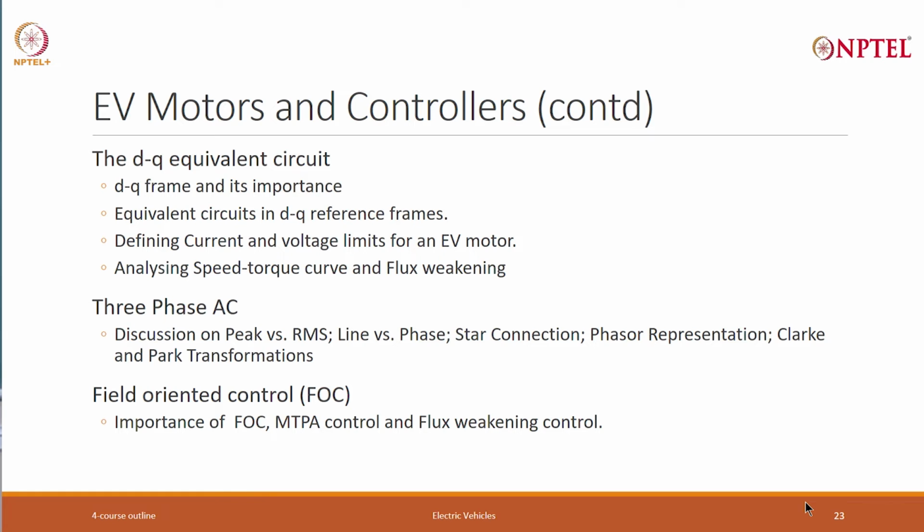We will then try to transform the electric vehicle parameters into what is called the DQ equivalent circuit, the DQ frame, and its importance. Equivalent circuit in DQ reference frames, defining current and voltage limits of an electric vehicle motor, analyzing the speed torque curve and flux weakening.